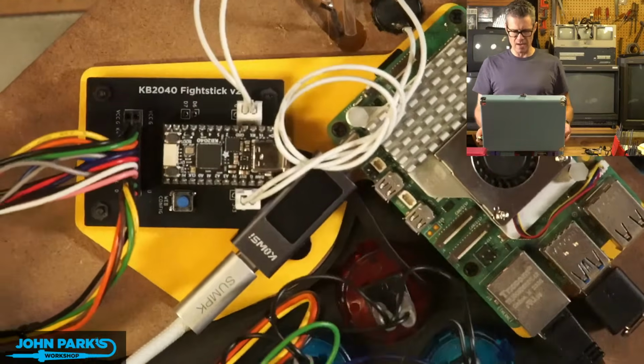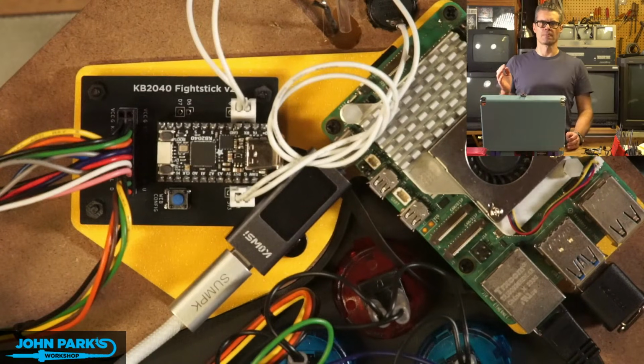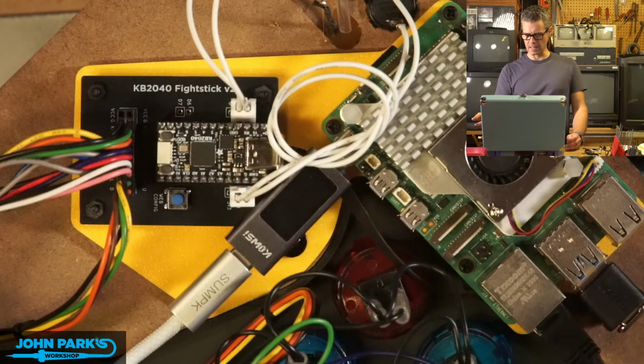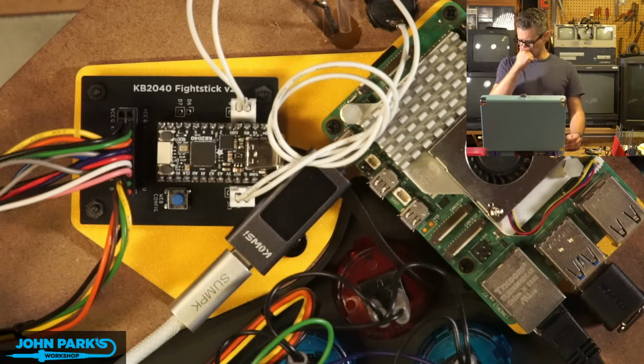Something else you'll notice, I started to run into some restarts or issues booting that were voltage sag. If you don't know, the Raspberry Pi 5 really does not like to start up or run anywhere below about 5.1, 5.08 volts. And so as I was getting these restarts, I checked the log. You could see that it was shutting off due to under voltage detection.